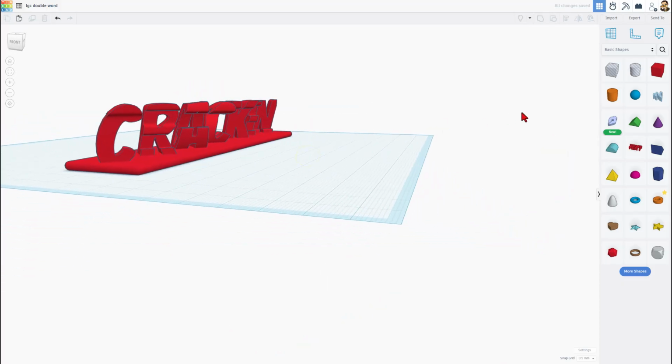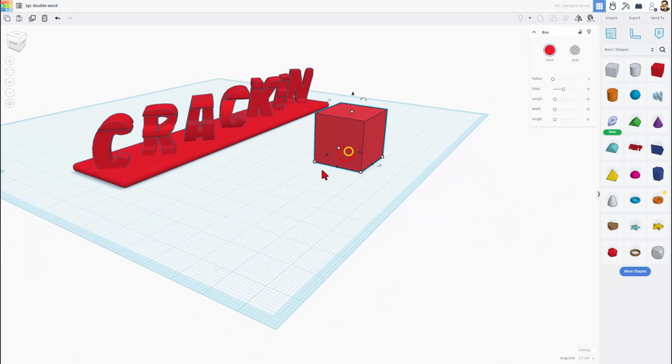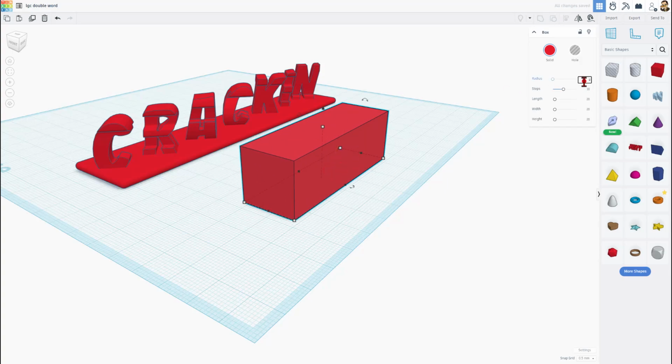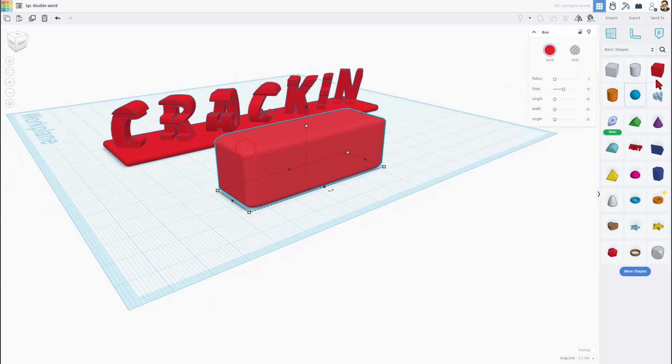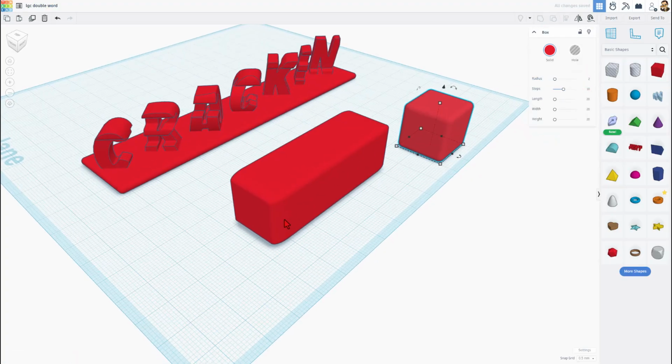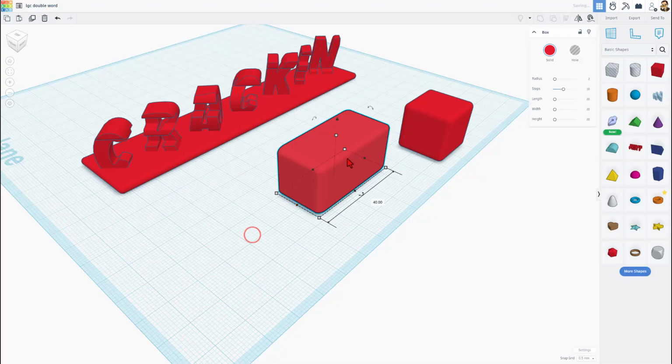The reason I highlight that, friends, is because if you bring these out and stretch the handles, this time I'm going to do a radius of 2, and check it out. It is not the same rounded shape that you start with. The moral of the story, friends, is if you stretch these handles, it can be super useful, but it breaks the parameters. See this distance of 40?